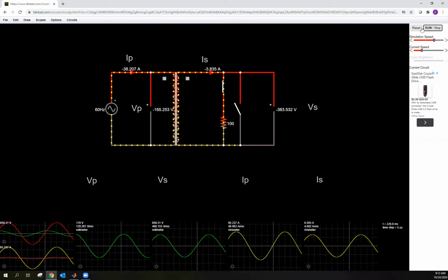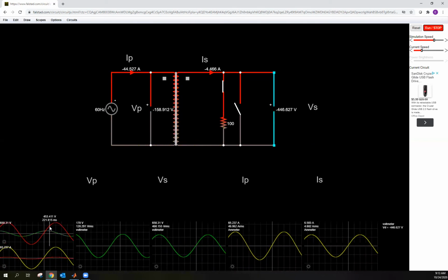Again, if I pause it, the phase lag of V2, which is here, or VS, and IS are in sync because it's just a resistor. So if I compare the phase lag of V2 to the voltage V1, that's equivalent to looking at the phase lag of I2 or IS to V1. And here we can see, look, nearly 25% or 18%, right? Okay, so here's the peak. This would be 25% if this peak or this 0 point was just moved over.